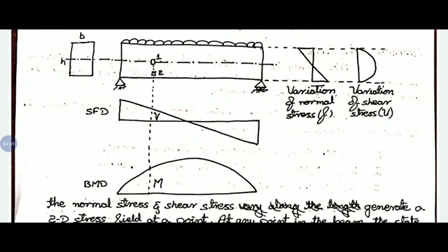So before the beam cracks, the stress carried by the steel is negligible. When the principal stress exceeds the cracking stress of the concrete, the concrete cracks, and there is a redistribution of stresses between concrete and steel. That is, the steel and concrete will balance the stresses.